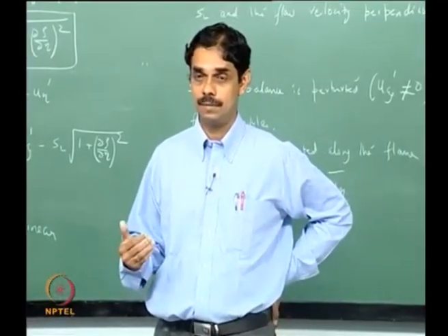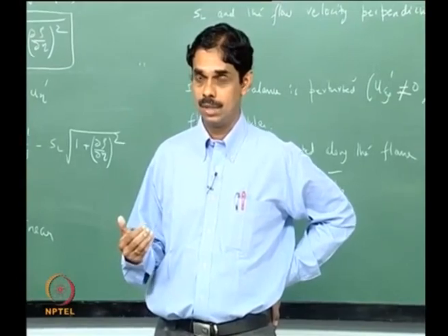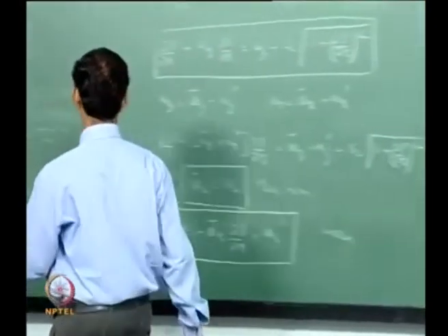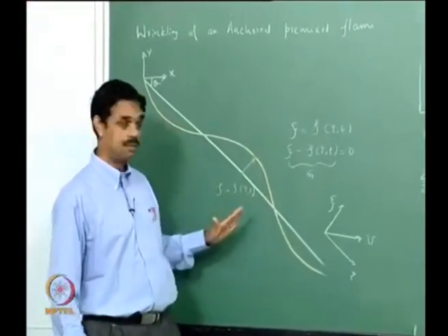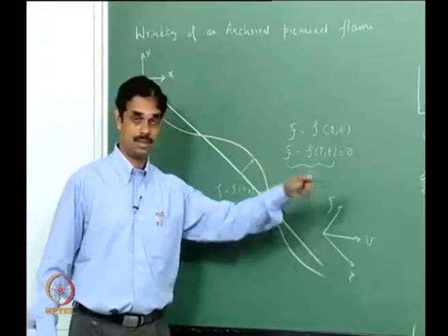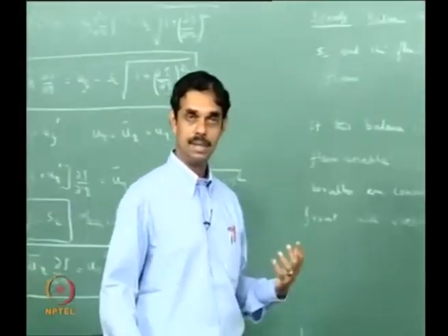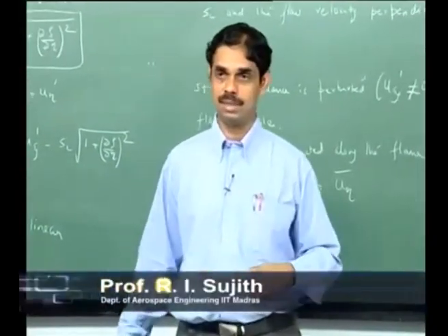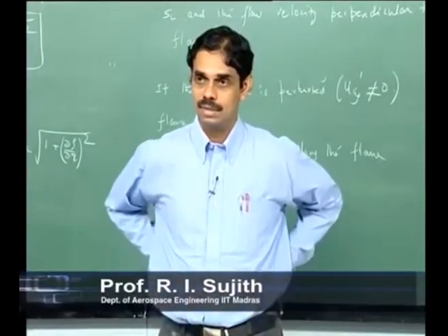Time lag will depend upon the flame shape, the angle. The flame angle determines the flame direction, the velocity along the flame, and the velocity across the flame. So clearly time lag depends on this, and we will do this in the harmonic domain, where perhaps the interpretation may be simpler, and we will look at what causes it and how we can make more sense of the time lag.